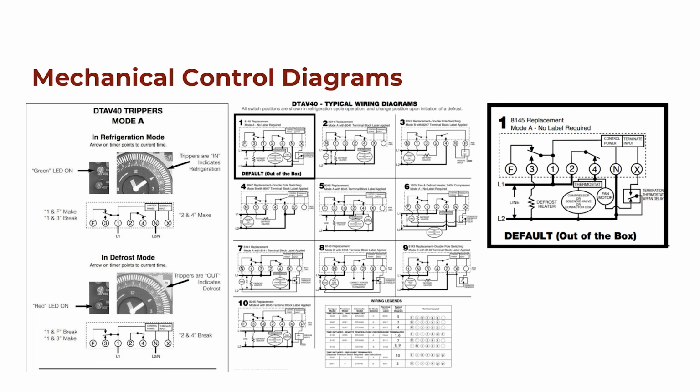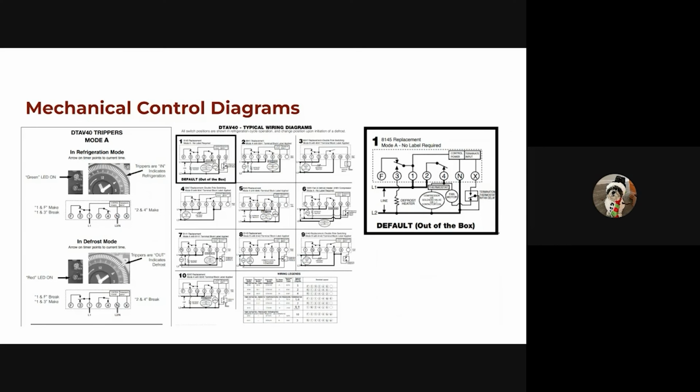So I would imagine that we would want to control when this compressor runs. In fact, I know it does, because I hear my refrigerator doing this. It turns on and off all the time, but it's not going into defrost mode. And so this thermostat must be maintaining the temperature. I don't know where it sits. I would imagine it sits on the suction line. Maybe Jason, do you know a little bit about that?